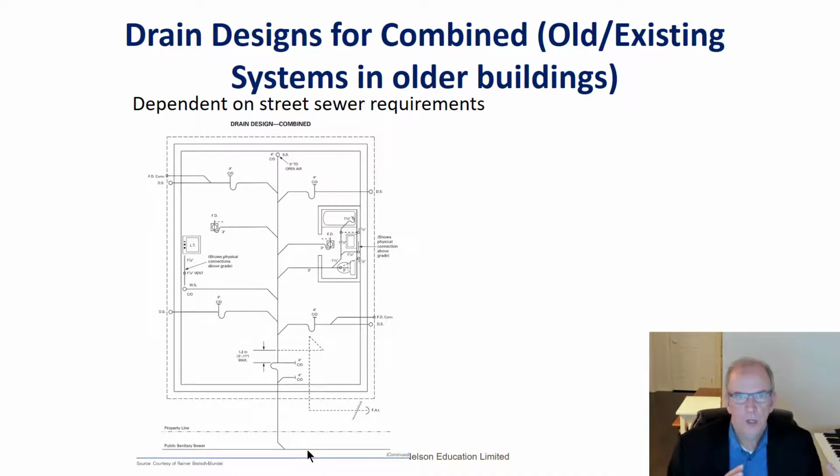We have two systems. So you have one for your sewage, and then you have one for your stormwater and cleaner water. Your weeping tile and your downspout water and the stormwater from the streets goes down in the storm system. That goes into the lake. Well, it's relatively clean water. The sewage water, what we call black water, goes into the sewage treatment plants, and then it's treated before it's let into the lake, so that it's not causing harmful bacteria and other issues.